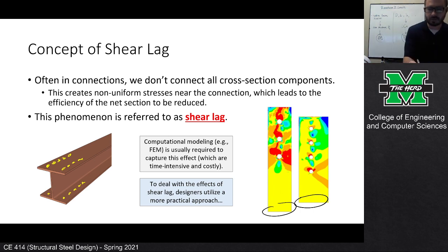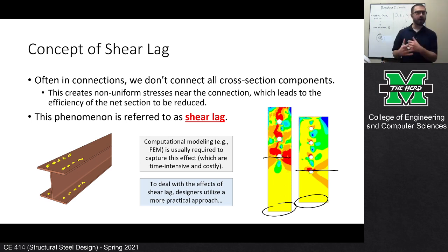But if you look right here, where the net sections are, the stresses are weird. They're not simple. They're funky. They're all over the place. It takes time for those stresses to propagate and distribute throughout the tension member. Out in the gross section, the stresses are pretty uniform, but right there at the connection, they're weird. They're difficult to handle. What ends up happening is,